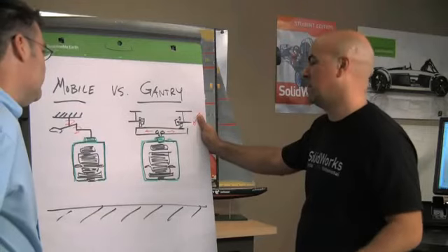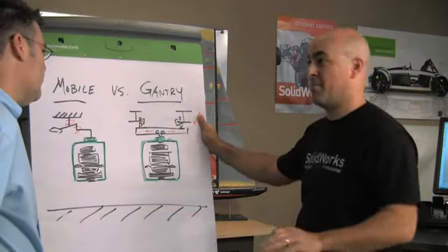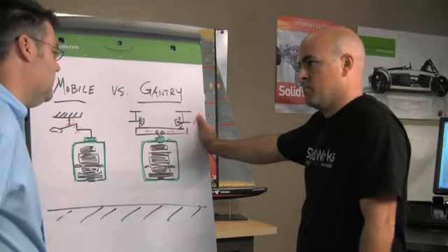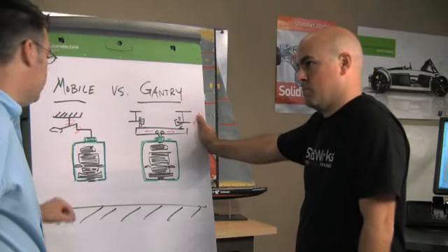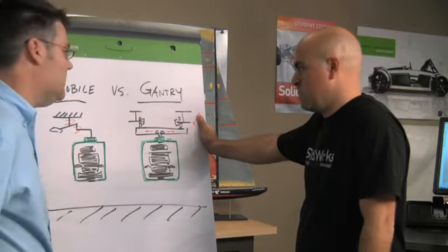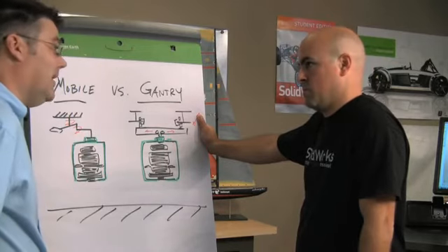Yeah, honestly, it'd be great to build both these designs and see which one we like better, but I don't have the time or the budget to build them both. Yeah, I think what we can do is get Motion to actually move these parts inside of SolidWorks. We can then calculate the loads, put those loads into simulation, do our stress analysis, look at the factor of safety of each of these parts, and that's going to tell you which one's safest of all. Okay. All right, let's start with the first concept, the counterweighted mobile.